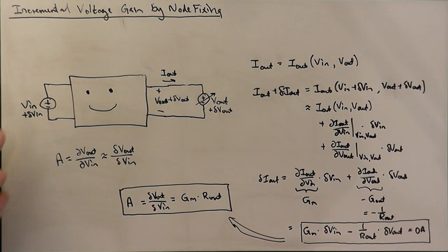And so this is another instance of divide and conquer. Kind of like we had when we had source splitting and superposition. We're using superposition here. This is effectively superposition, saying that we have two components or two sources, and we can compute by superposition the overall result of the circuit by the summation of these two separate components. This is a manifestation of superposition here.